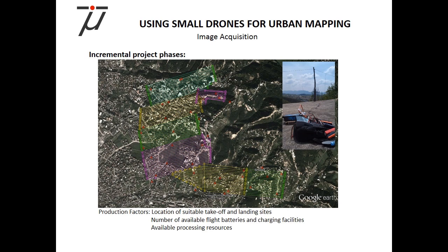And each one of those had a unique launch pad. That's important in this. This terrain is very hilly, so you have to design around what your flying height is going to be. If you want to maintain a somewhat uniform GSD across the terrain, you have these high structures, and none of it is modeled properly, so you don't really know what you're doing.